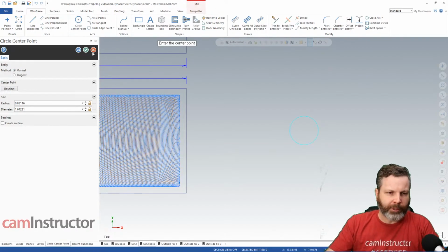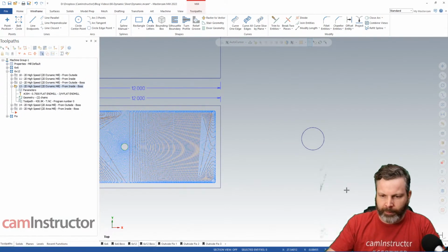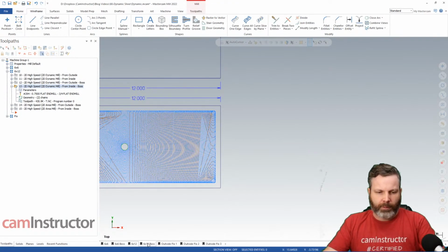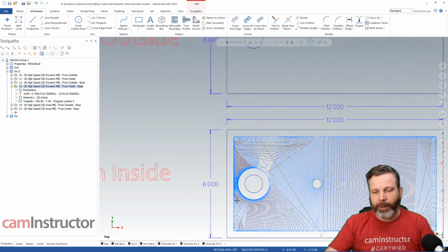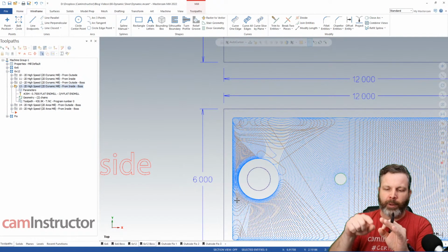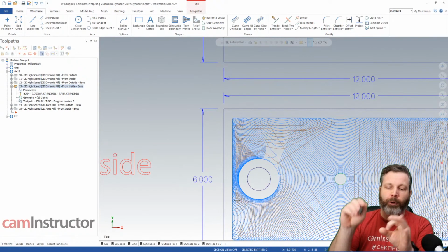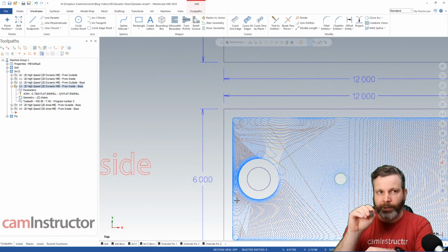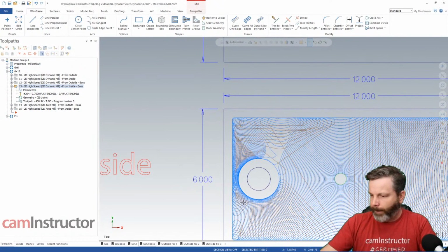I guess you don't really need to draw this stuff. I can just explain this with math. So basically, if we have a 3/4 inch cutter and we're making a .150 radius, we're programming the center of that cutter and we're making a circle that has a radius of .150. Let me bring up my calculator here.